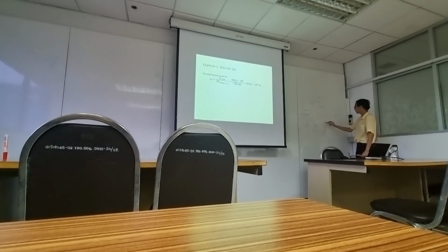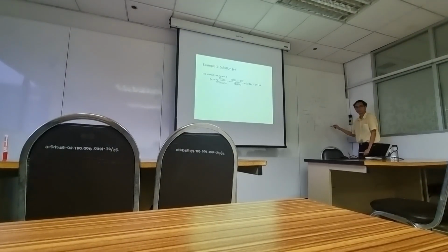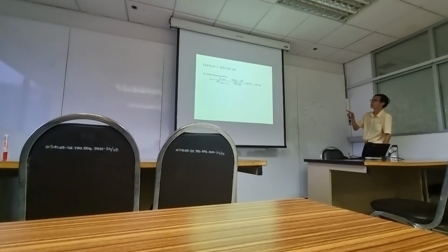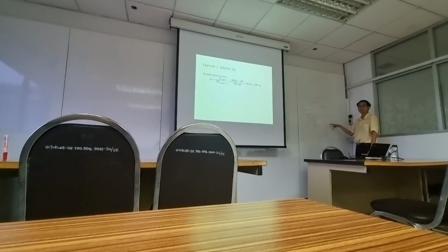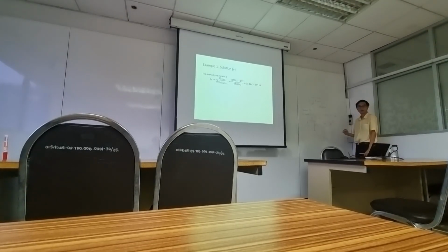So with this short circuit current, we have equations like this. The short circuit capacity, this is three-phase, equal to what? Because VS is at the rated value, and this is line to neutral, so you multiply by 3 for three phases.